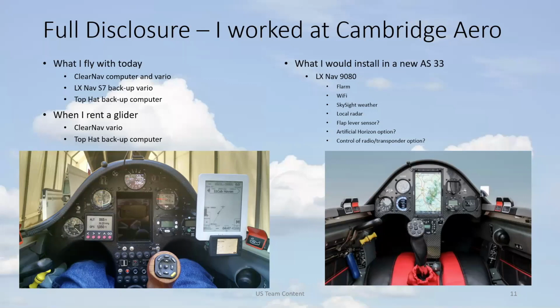Yeah, I have a PowerFlarm hidden away behind the panel here. On the left side, you can just see the antenna poking up at the top. The PowerFlarm has ADS-B and Flarm signals. When I look at my Flarm radar, I get both. And I believe with this Flarm Fusion, for the first time, we are wiping away the borders between the US and Europe, because I understand that Flarm Europe runs on a different signal than we do here in the US, and Flarm